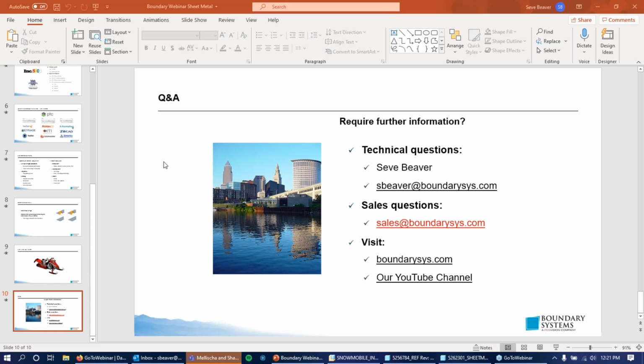Can you flatten formed parts as you can with other sheet metal features? Not sure I know entirely what you mean there. If you mean a flat pattern preview, then the answer is yes, if it can be flattened by Creo. Sometimes it will tell you that this cannot be flattened.